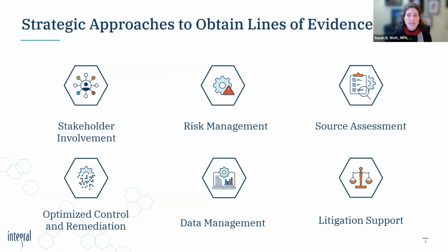Guidance documents indicate that groundwater, soil vapor, subslab, indoor air, outdoor air data, as well as the knowledge of building conditions and internal sources can be used to evaluate the potential for vapor intrusion to impact the indoor air of a building. These data serve as useful tools and lines of evidence and can indicate whether there's a potential or current complete exposure pathway.